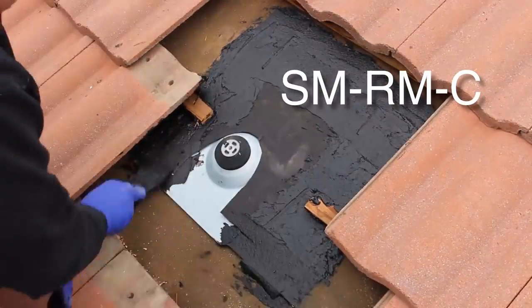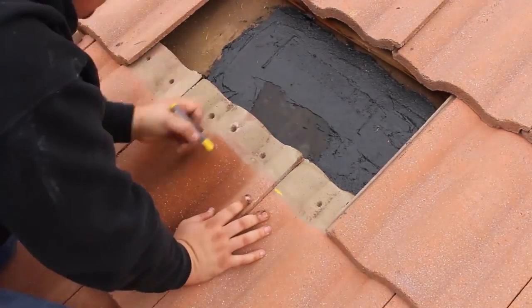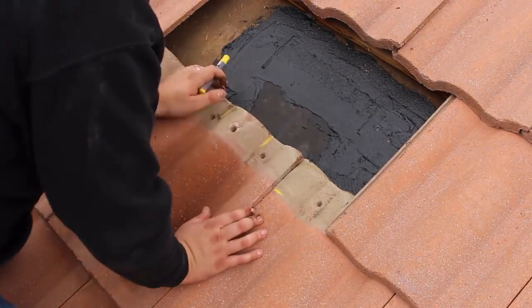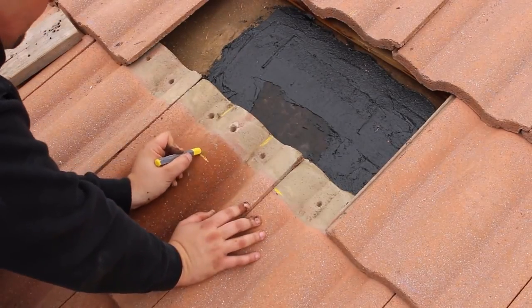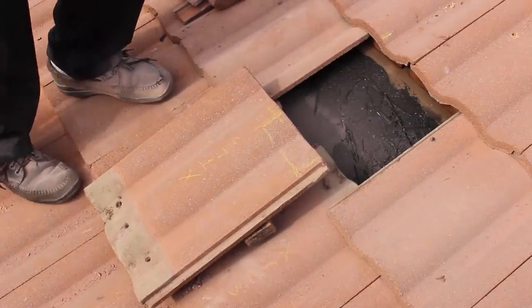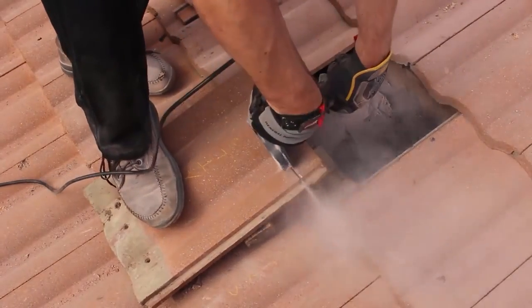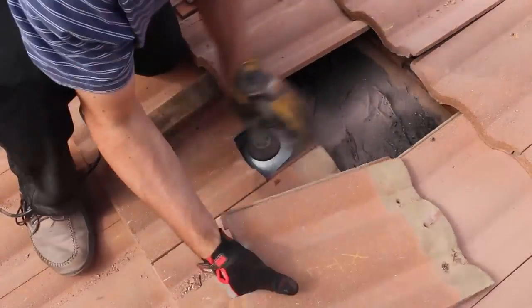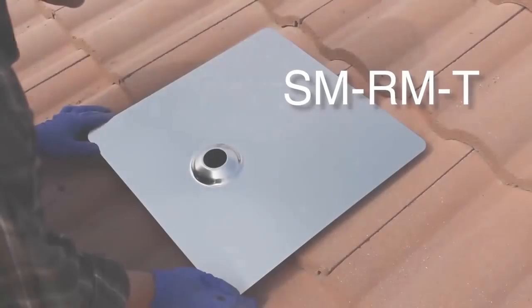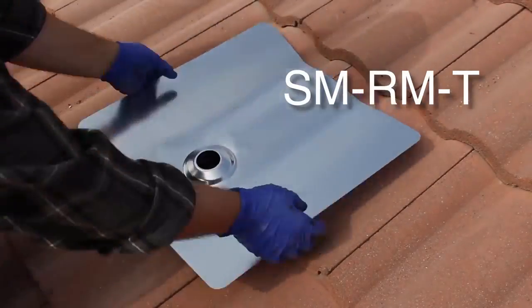to prevent any leaks. After the roof flashing is ready, proceed to insert tiles one by one as you measure, mark, and then remove them to cut a conservatively sized space through which the roof mounts will penetrate the tile. To cut the tile material, you can use an angle grinder paired with a masonry blade or a 2-inch masonry hole saw. Once cut, place the tile back into position. The final step is to shape the tile flashing to fit the contours of the tile material.